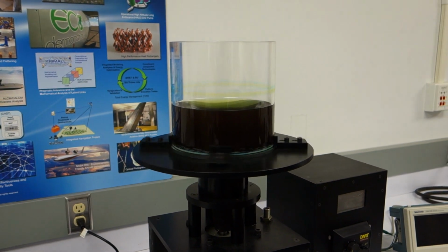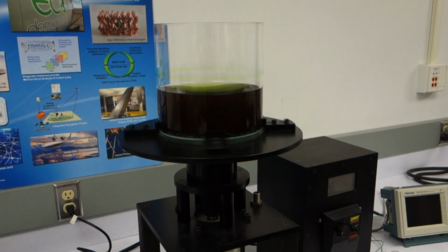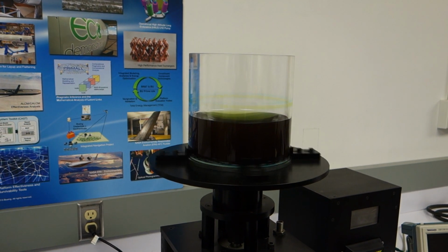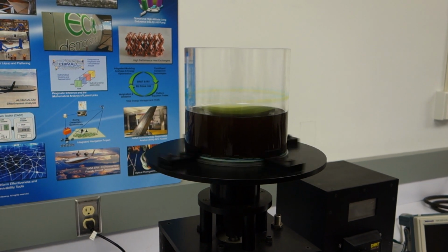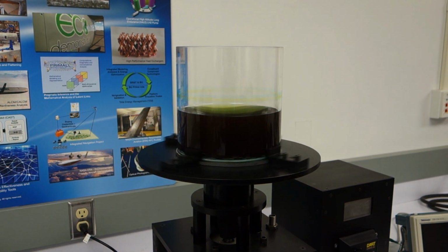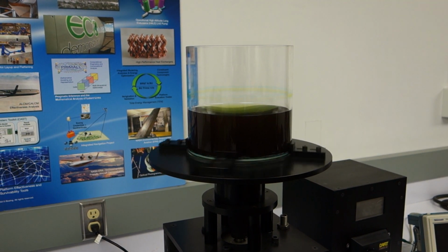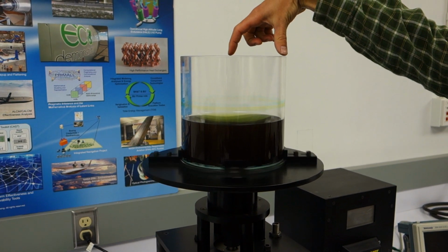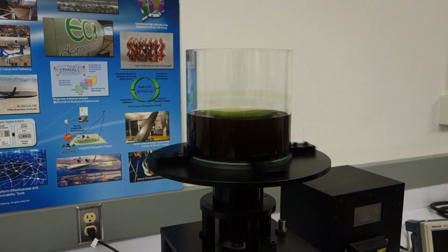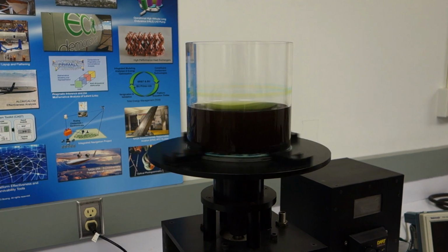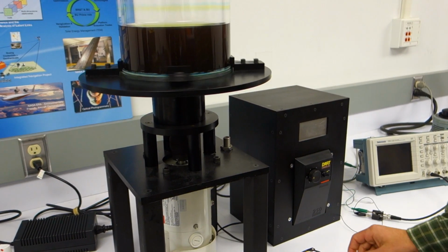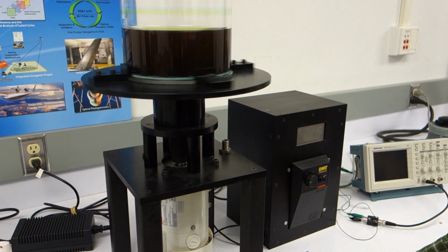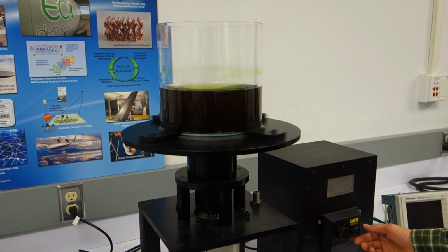So notice there that we're going to be reaching steady state, so this is rigid body motion. So the streamlines will be concentric circles emanating out from the center. And we are going to take as known values our radius of our tank and the angular velocity of the turntable, which we'll measure using an oscilloscope and an optical sensor, which we'll talk about in a bit. So now we've seen the setup, let's go back to the board and try to derive this shape.